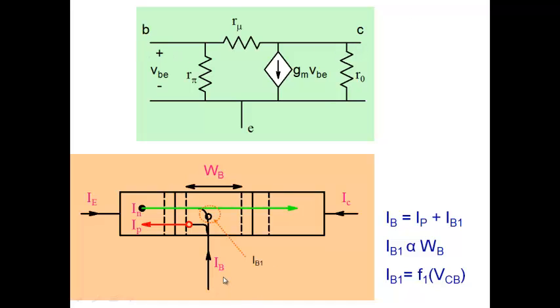So if I go inside the device, what I find is that the base current is coming from this terminal, and this whole region is p-type. So the aim of this current is to supply holes, because this region is p-type. Now, where do these holes go? Well, we have seen that the junction is forward biased, so the holes go here. That's one place where the holes are going, and the purpose of base current is to supply those holes.